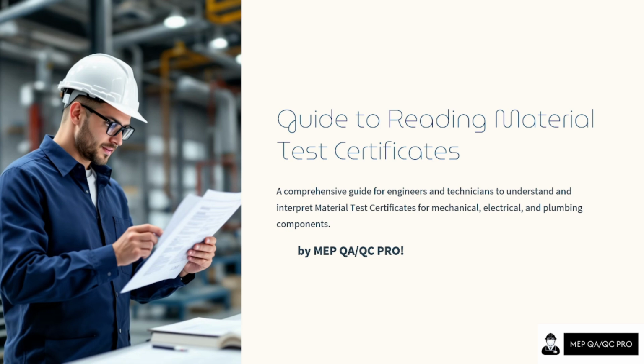In this video, we will guide you through how to read and understand a material test certificate as an essential part of QAQC documentation. Whether you are dealing with pipes, fittings or other construction materials, knowing how to verify the test results, standards and material properties is crucial for any MEP QAQC. We will explain what a test certificate is, what the key sections are, key terms, how to check compliance with the project specification, and common mistakes to avoid. So for all this, you will learn it here in this video.